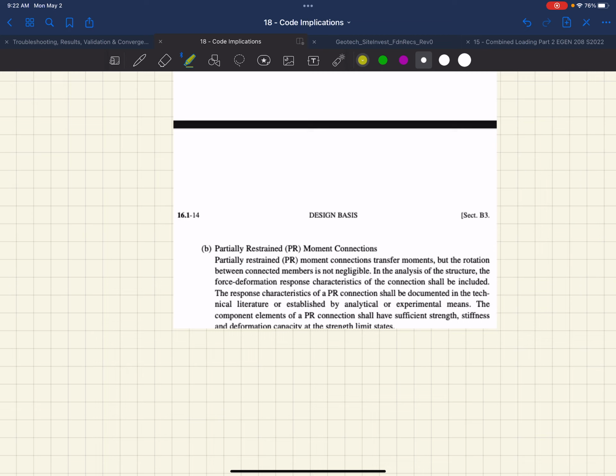Yeah, I would say the strength of the moment, I wouldn't necessarily say that it failed, Elias, as it has a reduced stiffness. So, like if you had a shear tab, like the connection of this beam to this column, right? It has a shear tab and it has bolts on it, right? The stiffness of this due to rotation, if we looked at it in section view, right? Now we've got these bolts that are going through this, right? The stiffness of this is a function of its thickness, right? bh cubed over 12 sort of thing, right?